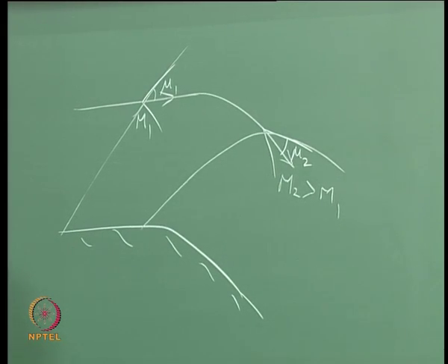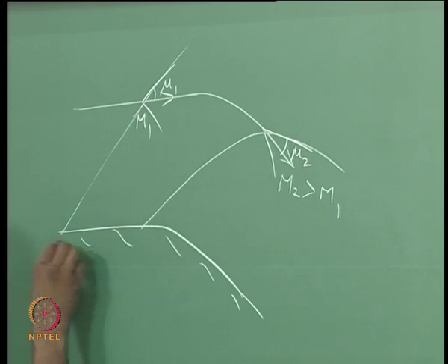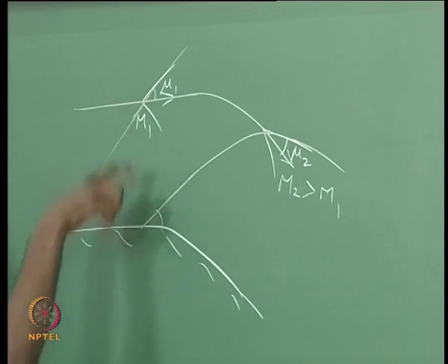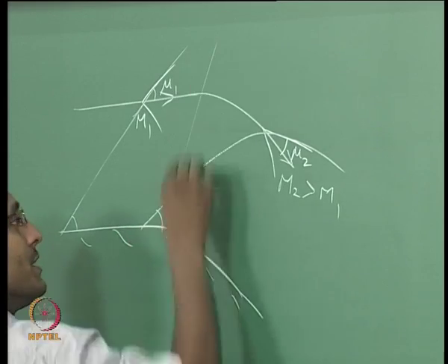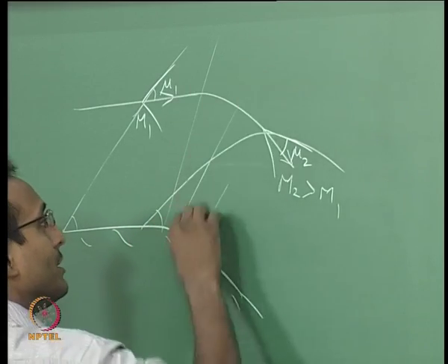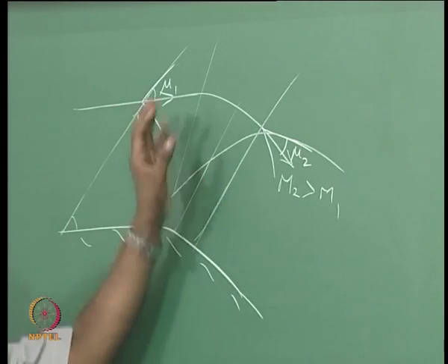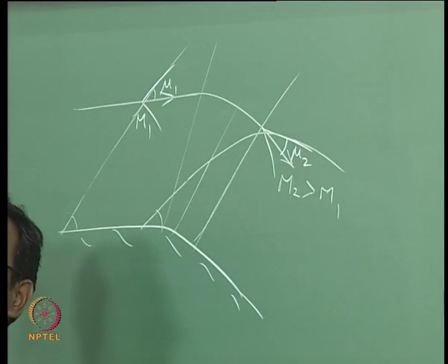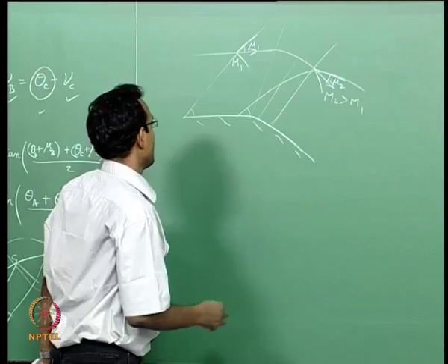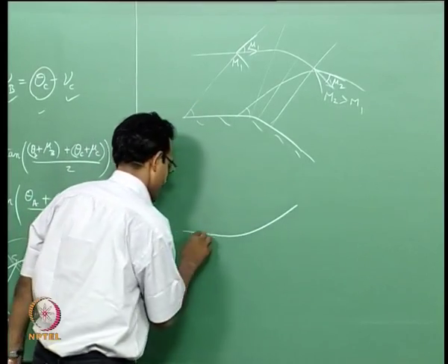Okay. What is really happening? I am having these two; they were initially the same Mach number, so they were the same mu1 value here, they were running parallel. Suddenly, because they are experiencing this expansion fan, this whole region, at the end of it, it is coming out with diverging characteristic lines.